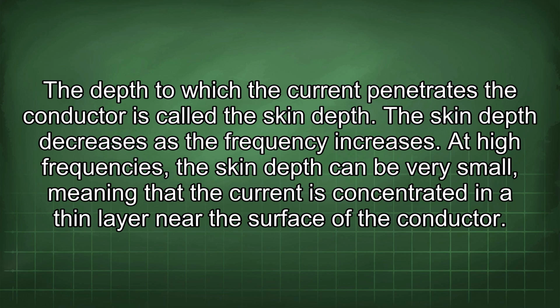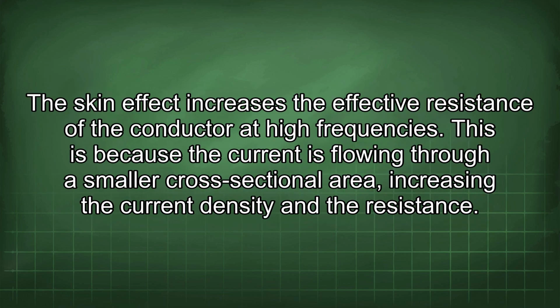The skin depth decreases as the frequency increases. At high frequencies, the skin depth can be very small, meaning that the current is concentrated in a thin layer near the surface of the conductor. The skin effect increases the effective resistance of the conductor at high frequencies. This is because the current is flowing through a smaller cross-sectional area, increasing the current density and the resistance.